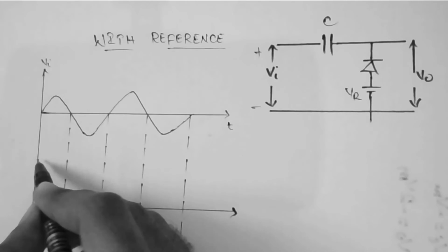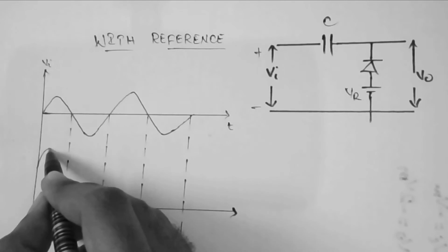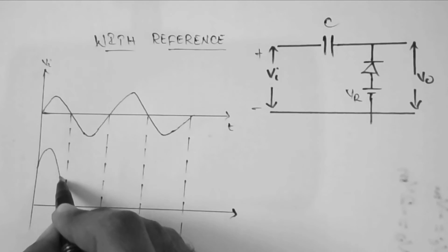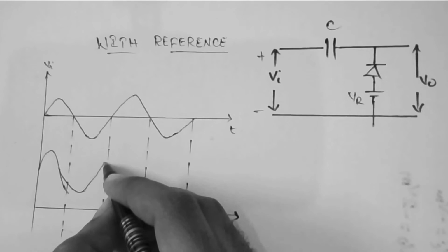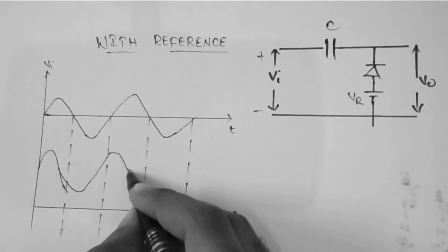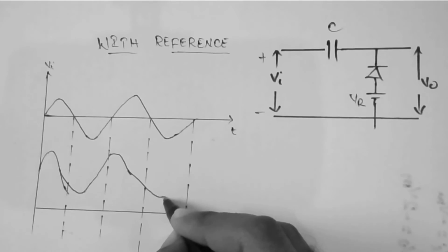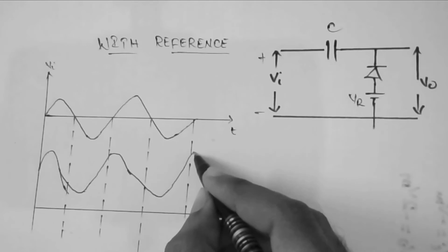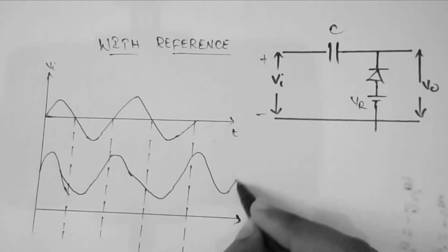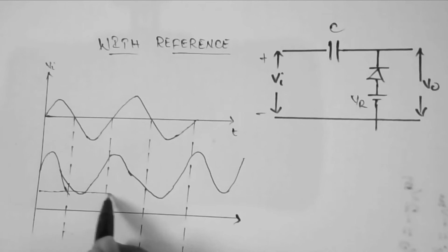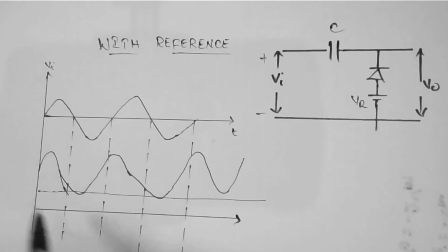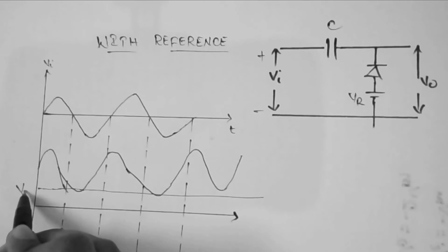Like the waveform would shift further on the positive side. So here the negative peaks of the input signal are clamped at the reference voltage.